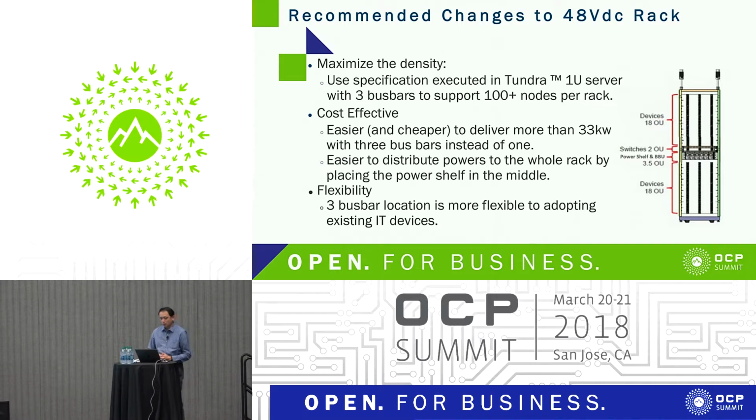It will be easier and also cheaper to deliver more than 33 kilowatts with the 3 bus bars instead of 1, because you don't need to make your material of the DC bus bar as much, and you can distribute that to the 3 bus bars from the mechanical and materials engineering's point of view. Also, it is easier to distribute power to the whole rack by using 3 bus bars as well.